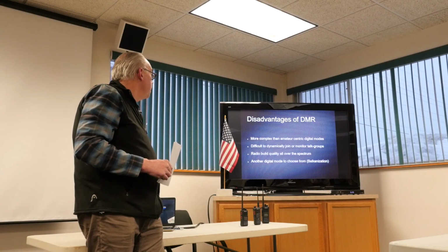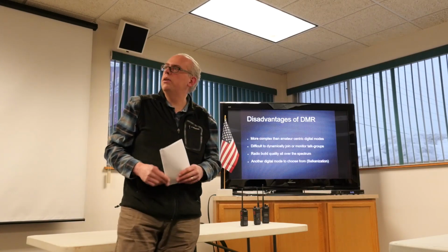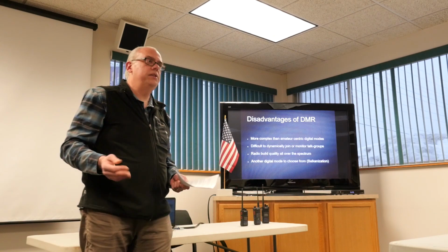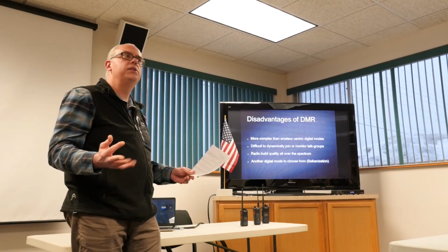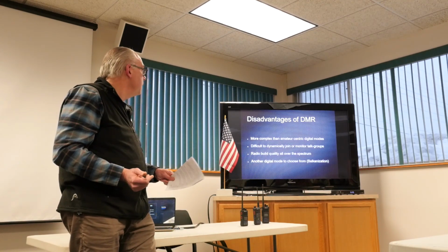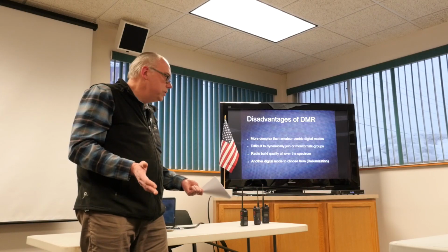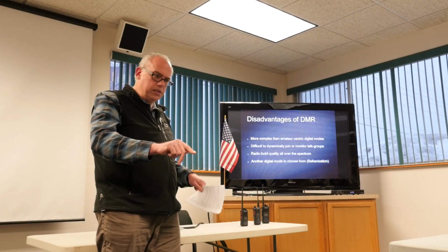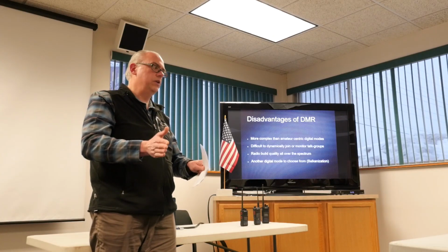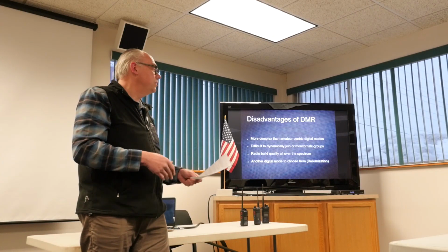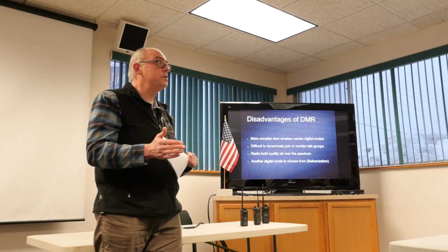Okay, so we talked about all the great things about DMR, but now what are the downsides of it? Because there's always two edges of the sword, two sides of the coin. DMR is more complex than other amateur digital modes. You know, Fusion is really neat because you can plug in your call sign, and you're on digital. D-Star is pretty simple.